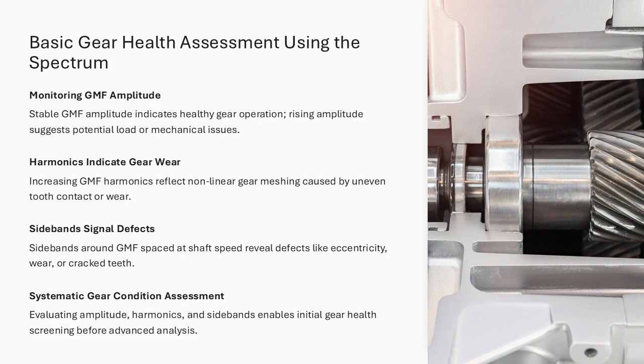Any deviation from this pattern warrants closer investigation, particularly when changes trend upward over successive measurements. An increase in GMF amplitude may be associated with increased load, changes in operating conditions, or developing mechanical issues. While higher load naturally increases vibration energy at GMF, unexplained amplitude growth under similar operating conditions can indicate tooth surface distress or alignment problems. Therefore, load context must always be considered when interpreting GMF amplitude changes.